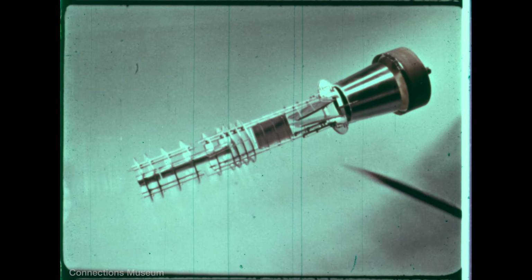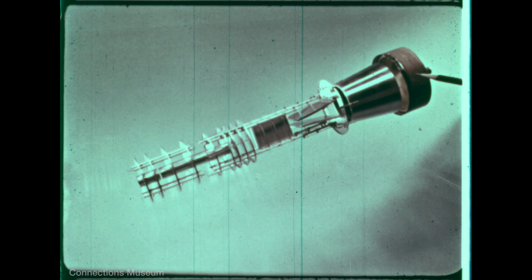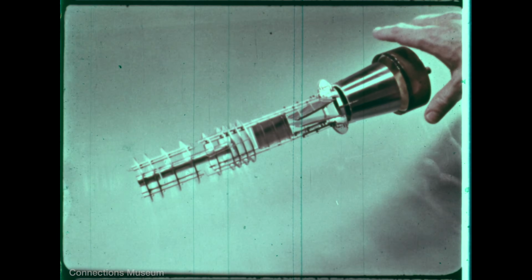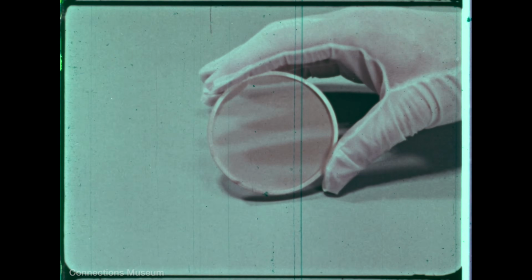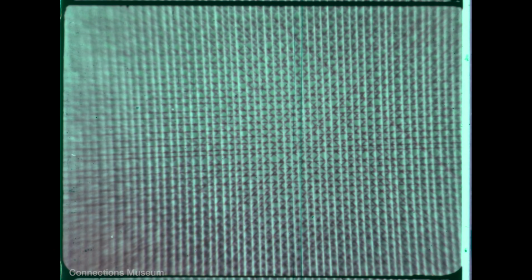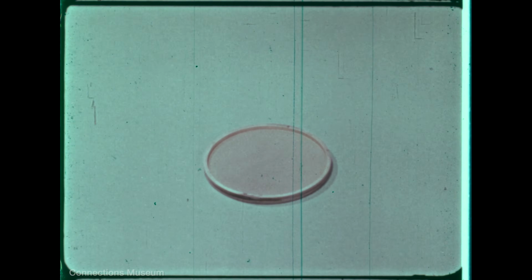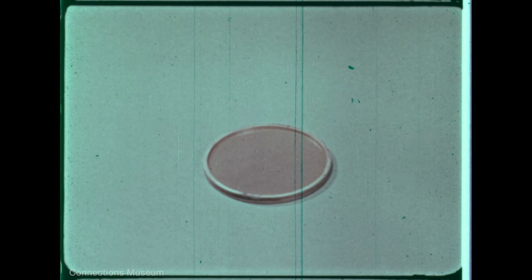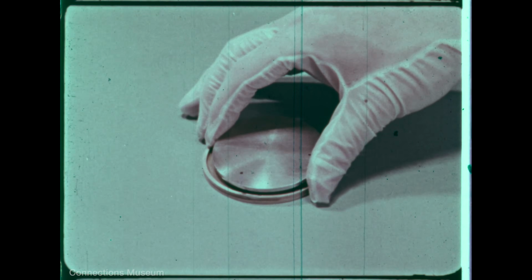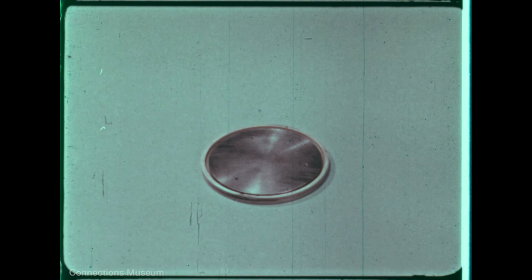The electron gun shoots a beam of electrons between deflection plates at the storage target, which consists of 3 elements: a very fine tungsten wire mesh from which the barrier grid tube gets its name, a mica disc on which bits are stored in the form of electrostatic charges, and an aluminum backplate which controls the relative potential of the grid and the mica.